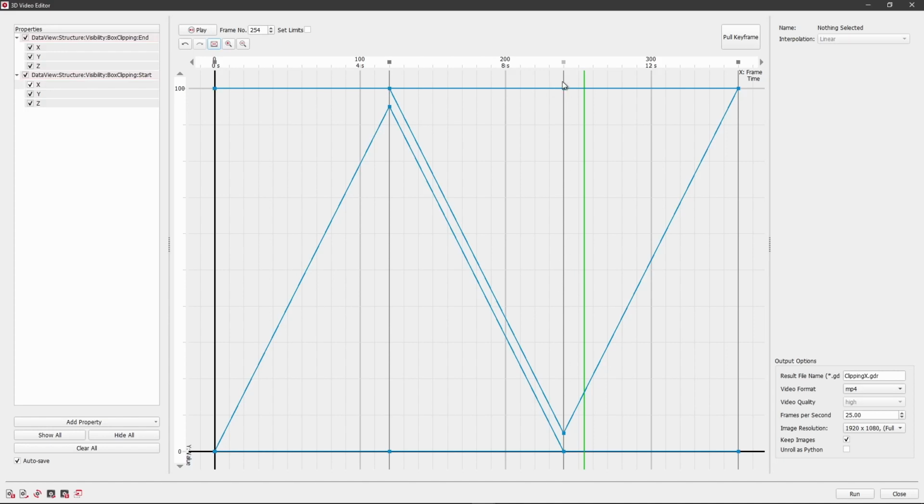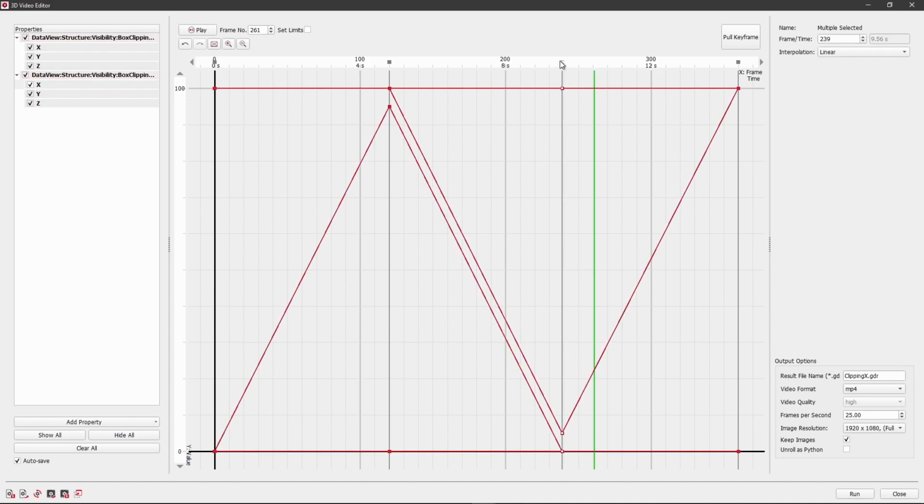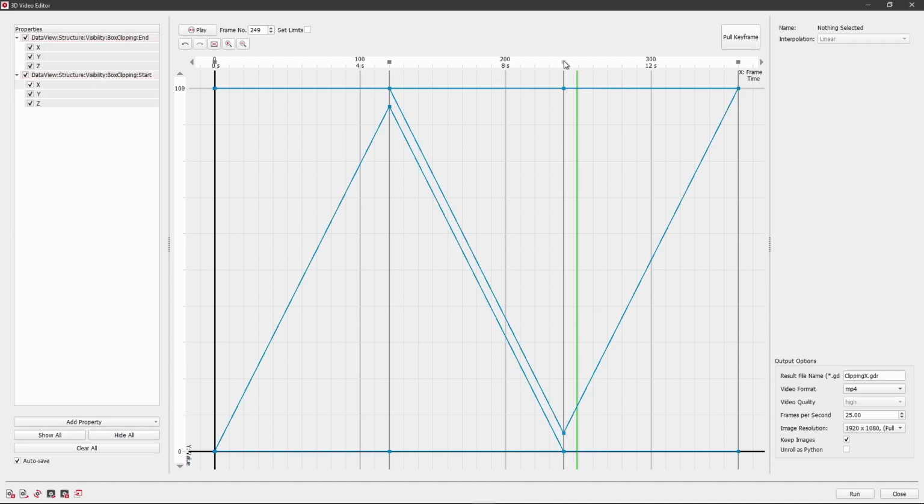Keyframes are groups in which the parameter control points are living in. Those are represented by a small blue box on the keyframe lines. A keyframe can be selected by left-clicking on the small dark gray box on the x-axis. By left-clicking and holding, we can change the position in time of the keyframe by moving the mouse left or right.